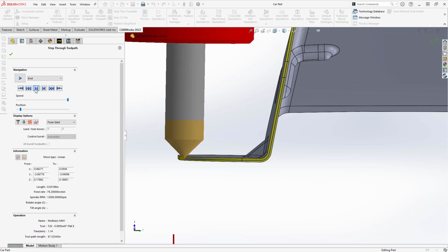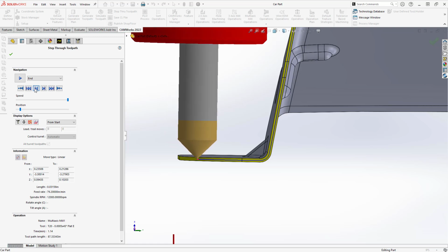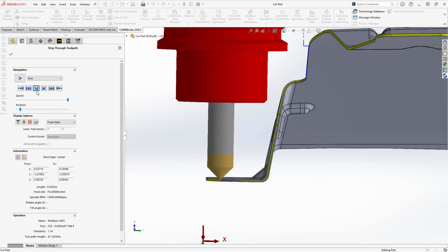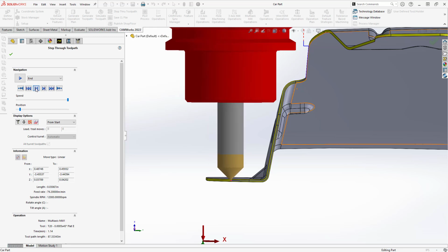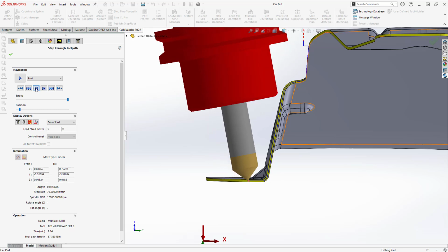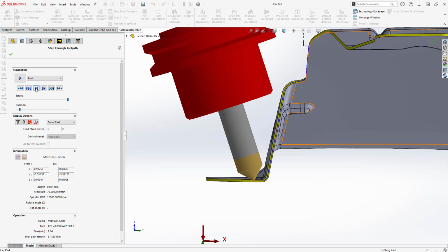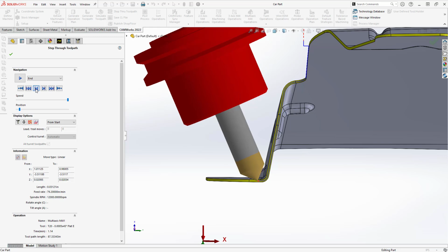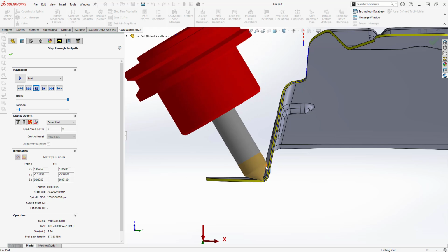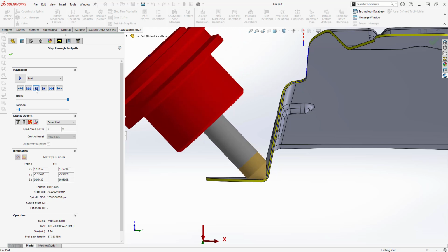So as you can see, it is orthogonal to the cut up until the point where the holder might touch. So it begins to tilt. And the holder might be enough to make sure I don't gouge, because as you can see, there's some distance there. But just in case, I also included the other bits there so that as it goes along, it makes sure that this also doesn't gouge right here. So that is the leaning away, that's the lag.